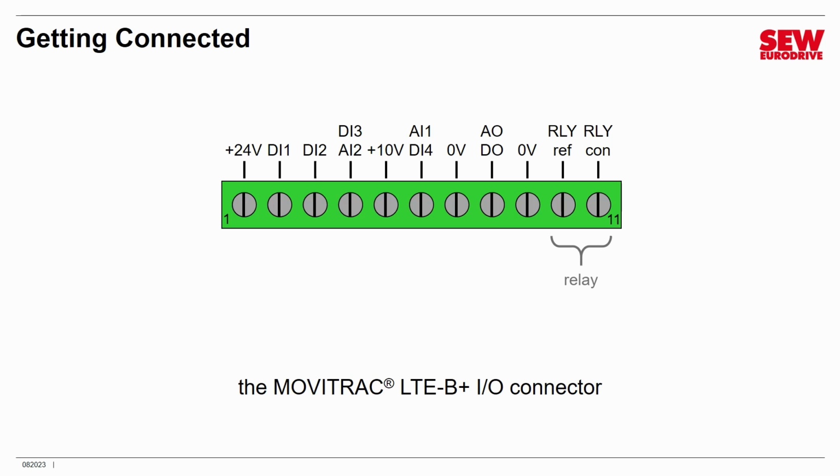And then finally, there is a programmable relay contact. The relay contact is a kind of digital output. If you wire it up to a power supply, you can use it for signaling. You can also use it to control a small device. It does have very limited current capability, so you can't do anything too hefty with it.